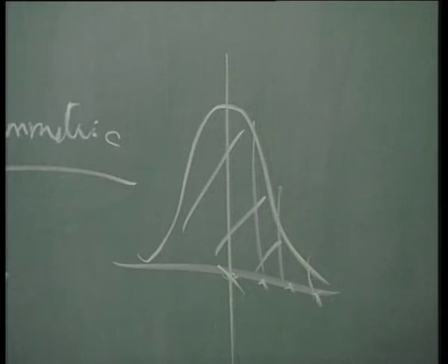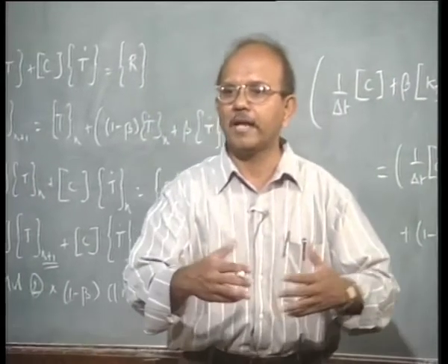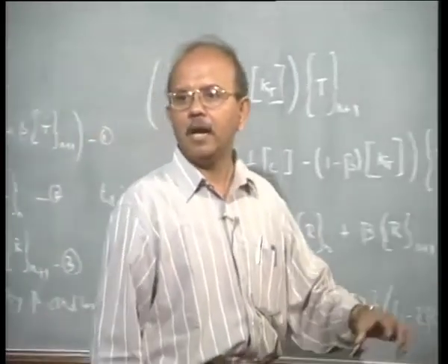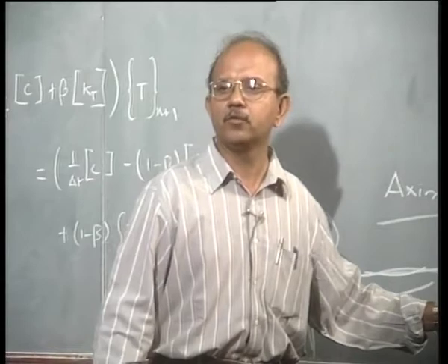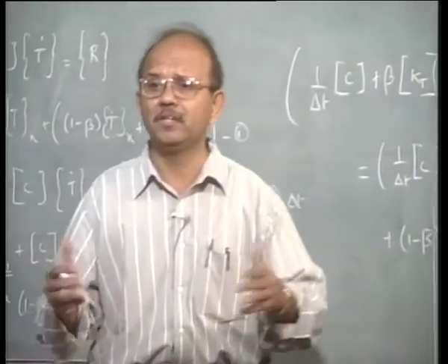In 3D it becomes bell shaped, in 2D it looks something like this. So this Gaussian distribution of heat energy starts moving. It's a moving heat source, so different nodes come into contact with this Gaussian distribution with respect to time, and the distribution itself gives a very good picture of how heat will go into the material.